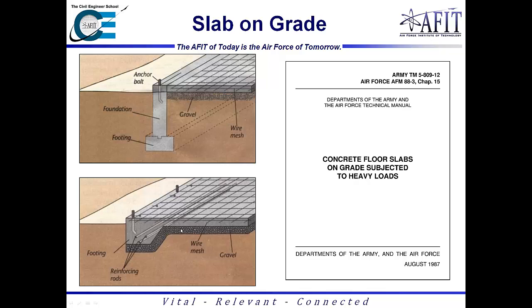With slabs on grade, one other way you could look at it is when you start talking about the actual grade beam down here, this beam will be thickened on the edge. Typically on the edge of a slab, you'll see this type of thing, unless you have an actual strip footing going on as you see in this picture, in which case these will just butt up against each other, and they may be anchored in as well.